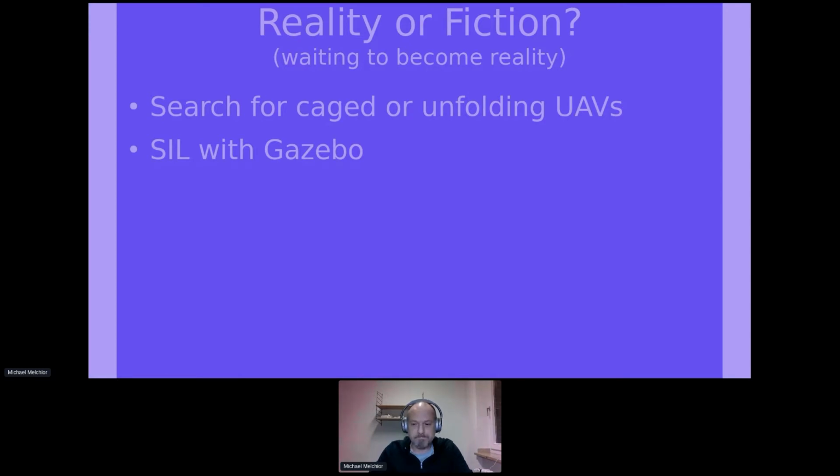So I went ahead and did some hardware-in-the-loop simulation with an old PixHawk that I had lying in my drawers, something that I also mentioned in my application for that talk. And also the PixHawk was doing well with that setup. So throwing something up in the air with a PixHawk and PX4 installed in it apparently was able, or should be able, to recover that rotational force and stabilize itself and do whatever you tell it afterwards.